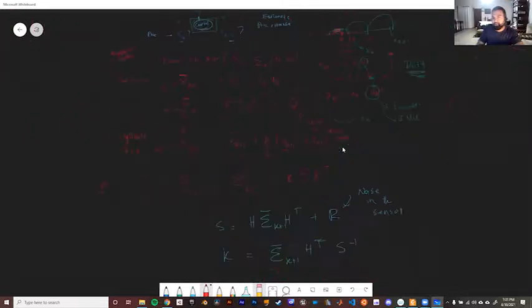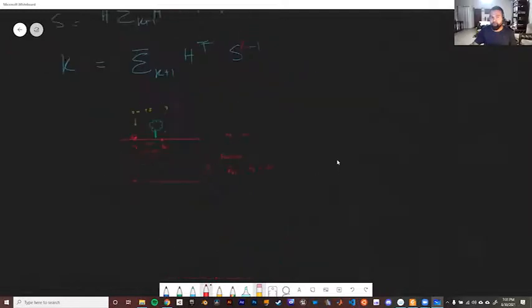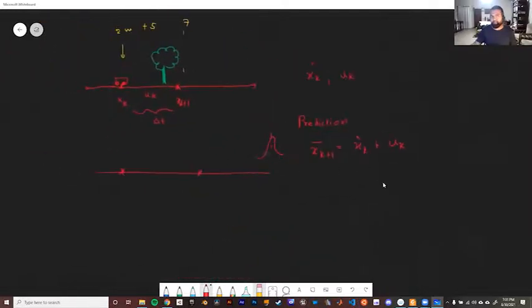This is that noise, right? How much the control signal is varying. Okay. All right, so this is our prediction step. So we predicted that the robot has moved forward in time, right? Based on this control signal. Now, will this prediction be accurate?